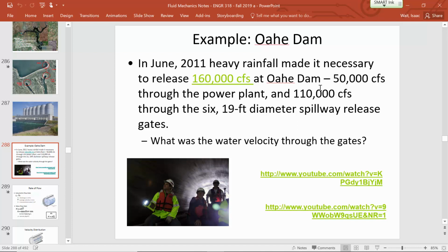So really all of Chapter 5 is applying this formula. In fact, the entirety of the second exam covers a relatively small number of equations. If you know how to use acceleration, so there's the equation for convective acceleration, that's one, Euler's equation, Bernoulli's equation, rotational flow, continuity, and then in Chapter 6 we're going to do one related to momentum. So there's really only 7 or 8 equations that apply to the entire second exam, and all of Chapter 5 is built around Q equals VA.